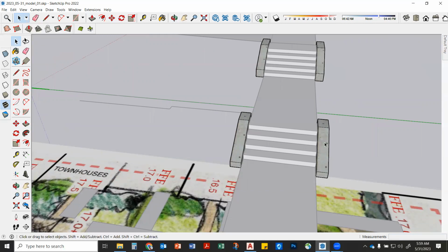You can make components. So if I've made components, but then I need to take those components and I need to change them without changing all the others. Yeah. So there's a way to do that. You select those components, you copy them, and then you say make unique. So there's still a component, but now they're a separate component. Instead of being stairs 02 or walls 02, now they're going to be walls 02B or walls 03. So there's still a component.